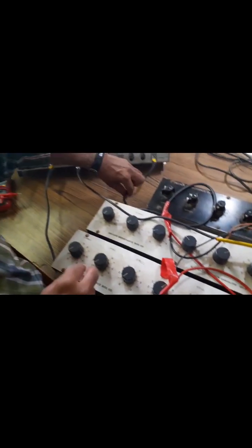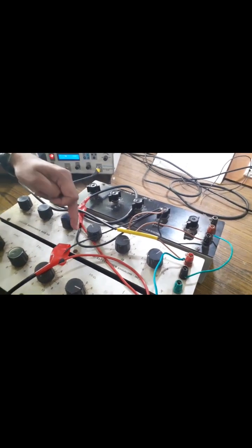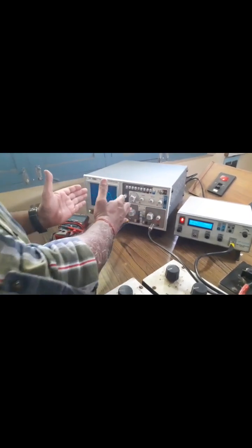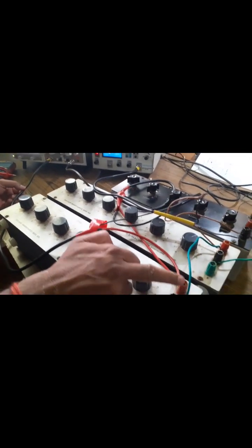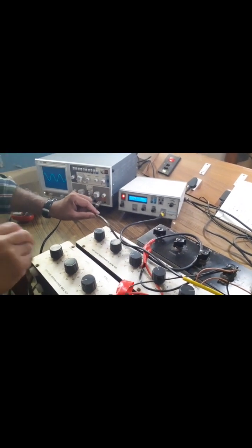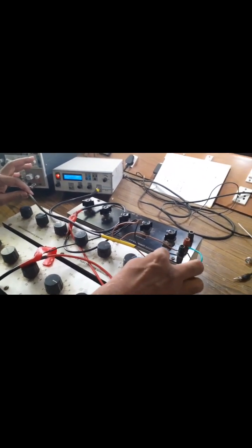And input from the signal generator is fed to the R1 point, and by default the other terminal of your probe should be connected to the reference point. In order to observe both input and output simultaneously on the CRO, I am using two probes, and this is your input channel. It is connected to the point where the input is fed, and the other point by default is connected to the reference. Similarly, the other channel we are using to observe the output. The positive terminal of the probe goes to the junction where R1 and R2 are meeting, that is nothing but this point or this point. So I am connecting it here, and the other terminal of the probe is connected to the reference. So your circuit connections are over.